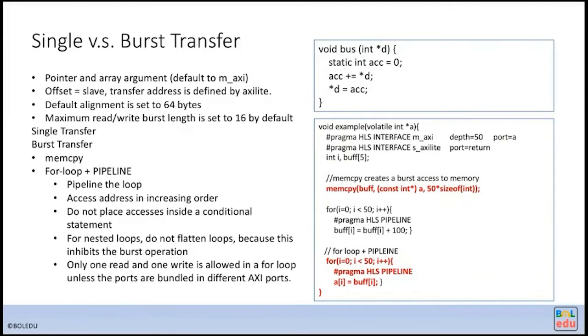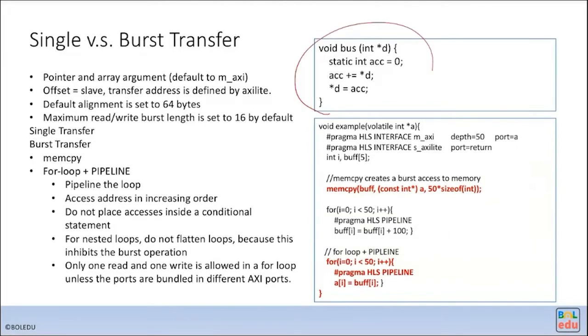And you will know that to use the DRAM, in order to have a higher utilization on the DRAM bus, you like to use burst access. Because if it's not burst, it takes a longer latency to access the data. If you just access a very small amount of data, then you can imagine the DRAM bus utilization will be very low. So in here, that's a pointer.